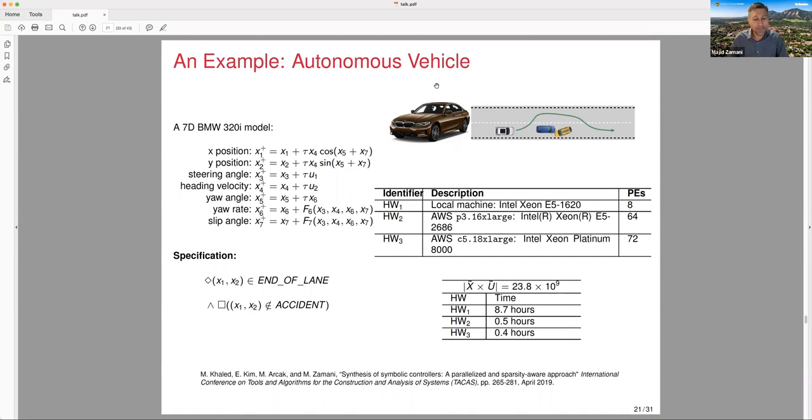So we know that this 10,000 dimensional system can be broken into a composition of 10,000 scalar subsystems. For a scalar subsystem, I can deal with it much more easily using sum of squares optimization, and I can search for sub-barrier functions for a scalar and find them much more easily than searching for a barrier for 10,000 dimensions. There is a complexity with the dimension, so we are not able to search for a barrier for a 10,000 dimensional system. That's the reason we need to break it down to the level of subsystems, search for sub-barriers, and then compose the barrier. Then we can ensure that their composition is a barrier for the interconnected system. Does it make sense, Ryan?